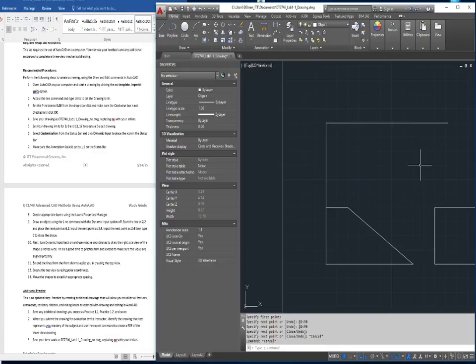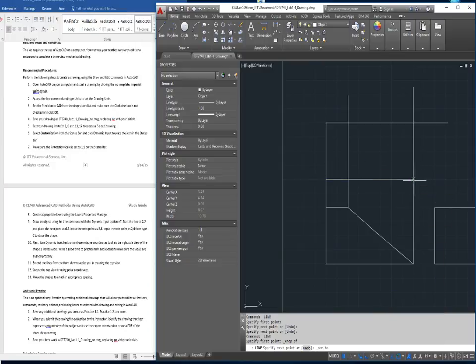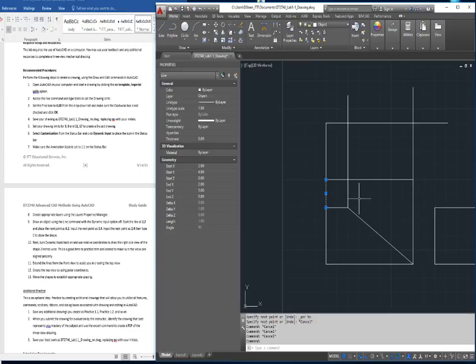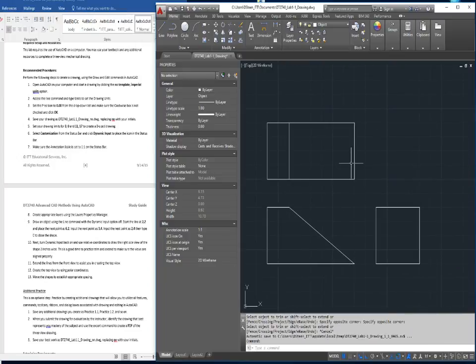I'm going to drag that over. Then all you got to do is draw this stuff up. Draw a line from that endpoint. Yeah, I kind of like the perpendicular, so you shift right click to get those. Now this one, can't trim it. Delete it. The other ones, trim, enter, enter. And there, that's what you should be turning in to me.